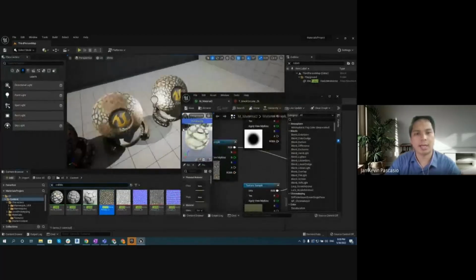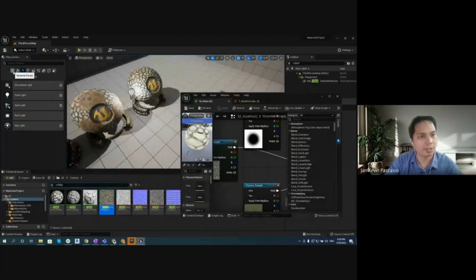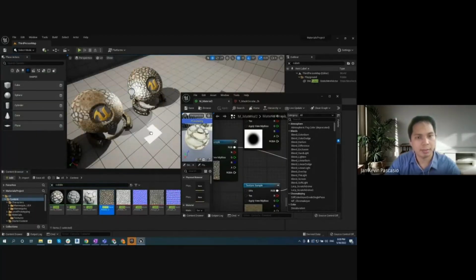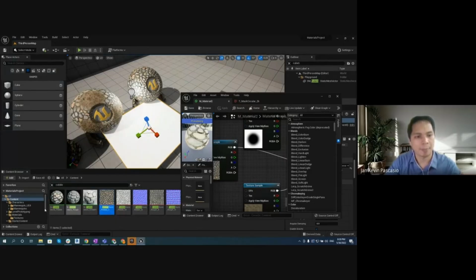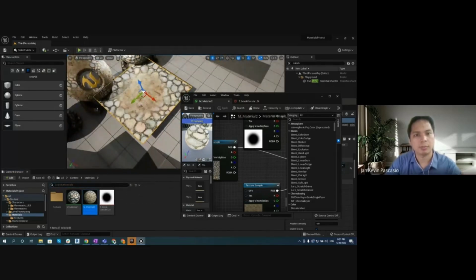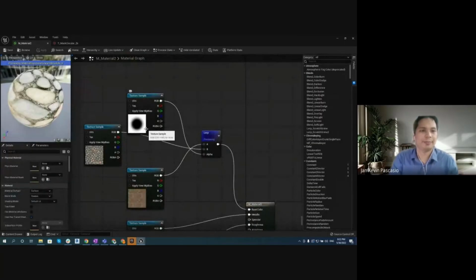Then I think it's best if we can just simply create shapes, a plane here. On your place actors panel, just create an actor and then scale it in X and Y. And then apply your material to it. Everyone still following? Yeah, wait up. Okay. But I'll show you a shortcut rather than drag and drop everything and then creating an actor.